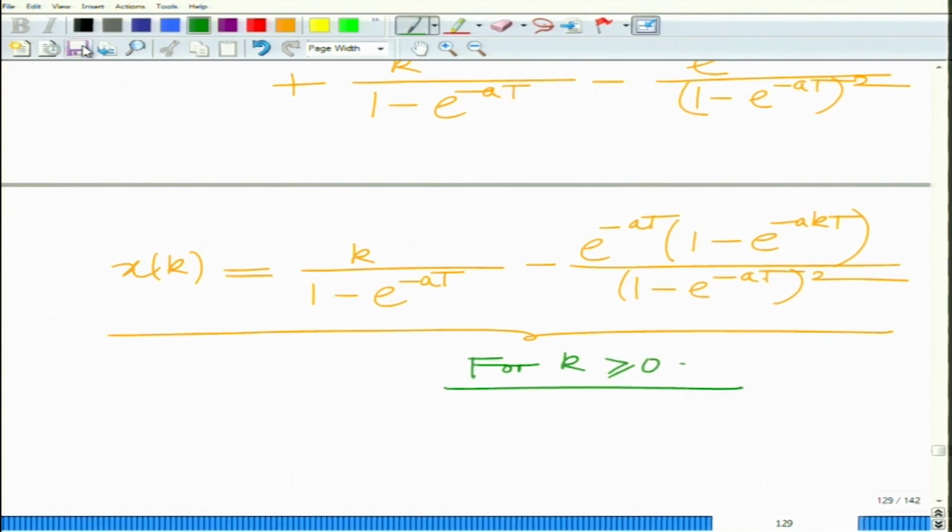Okay. So, basically that completes the problem. All right. So, what we have seen here is a different technique to evaluate the inverse Z transform, that is using the general inverse technique, also known as the method of residues, that is evaluating x(n) as the sum of the residues at the poles of X(z) into z raised to n minus 1, and we have seen a couple of examples to understand this technique better. All right. So, we will stop here and continue in the subsequent modules. Thank you very much.